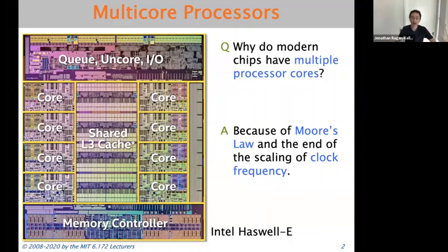Some basic architectural optimizations that we talked about a few lectures ago do a pretty good job of that. So, a little bit of superscalar execution, out of order execution, speculation, throwing some logic at building branch predictors. That works great at the beginning, but past some level of complexity, you get sublinear payoff. If you make your branch predictor twice as big, you don't wind up running your processor twice as fast. If you make your superscalar window, the number of instructions that you can execute in parallel, twice as large, you don't generally get double the performance.